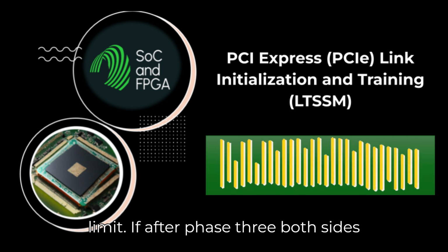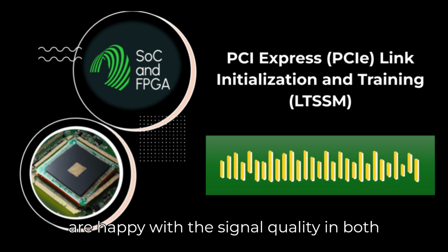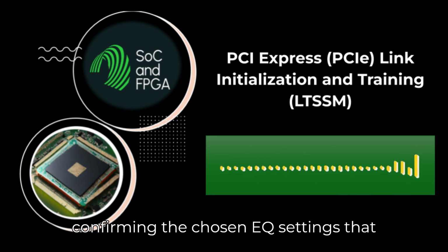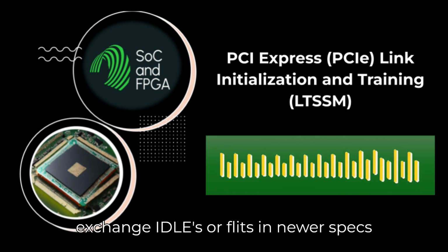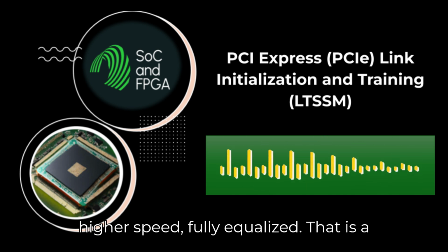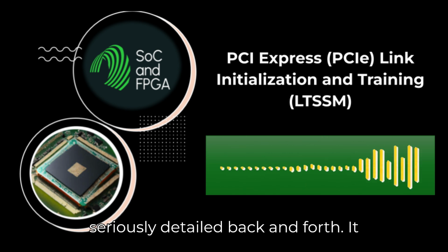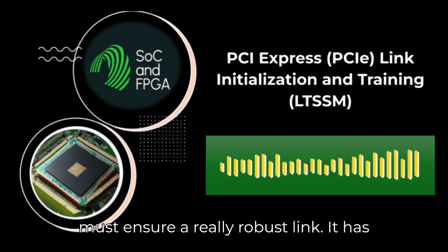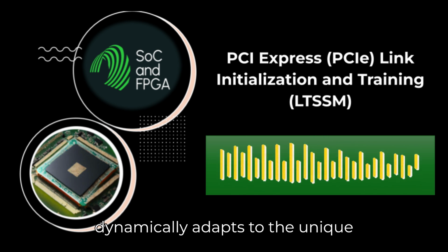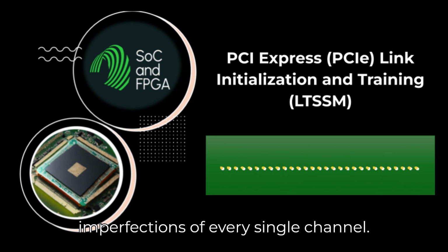time limit. If, after phase 3, both sides are happy with the signal quality in both directions, they exchange final TS2s confirming the chosen EQ settings, then exchange IDLEs or flits in newer specs, and finally transition to L0 at the higher speed, fully equalized. That is a seriously detailed back and forth. It must ensure a really robust link. It has to, especially as speeds climb. It dynamically adapts to the unique imperfections of every single channel.